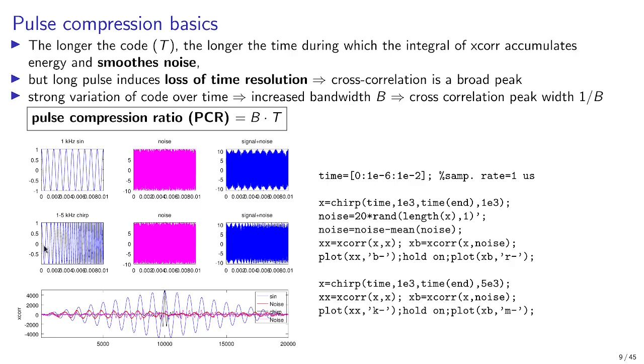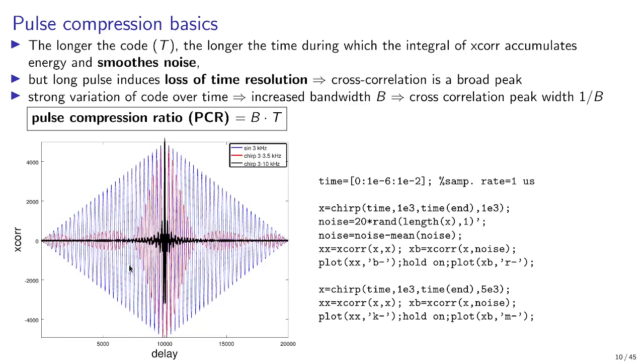On the other hand, if we do have this chirp, then the correlation only occurs when the chirp overlaps the pattern, and we see that only a single correlation peak results from such an analysis. In general, we can see that a uniform window will have high averaging capability but no timing capability, and the broader the chirp, the better the timing capability.